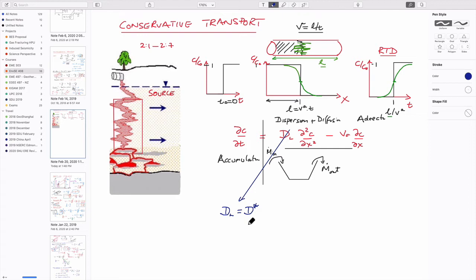It's not being carried by anything, but by Fick's law it's trying to get rid of this imbalance, a big concentration gradient of ink in the middle, by spreading out until all of the milk becomes light blue if it's a blue ink. And plus a component which is this dispersion coefficient multiplied by an advective velocity in the x direction or whatever. So this part here is diffusion, and this part here is dispersion. In other words, mechanical mixing.